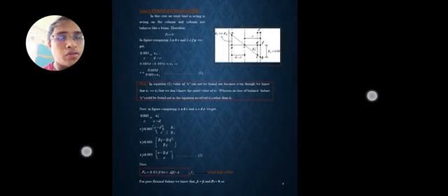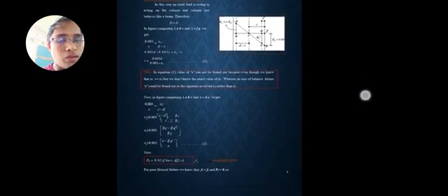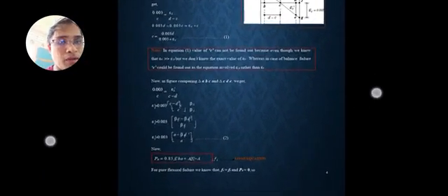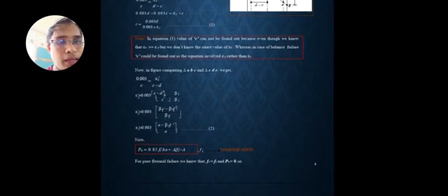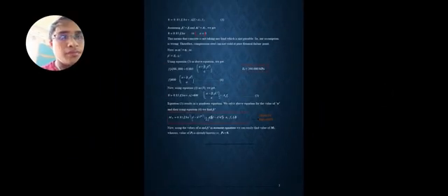So now, the load equation is P_n is equal to 0.85 f_c' b a plus A_s' f_s' minus A_s f_y.